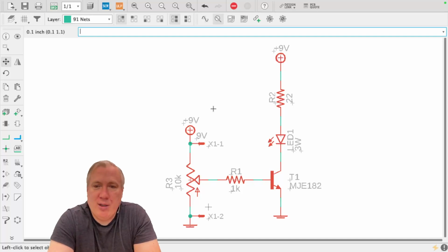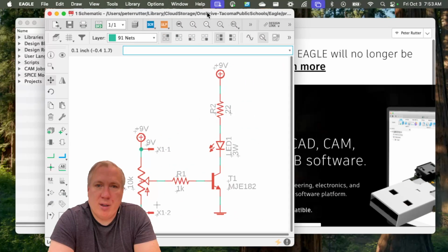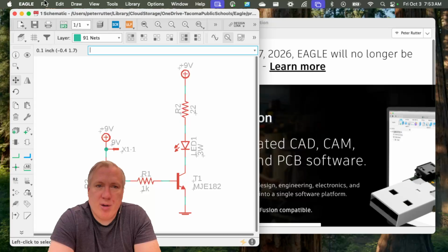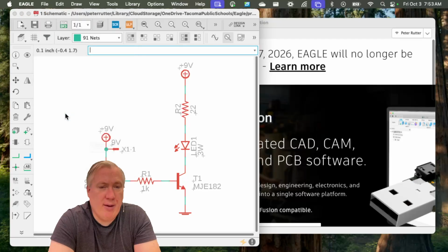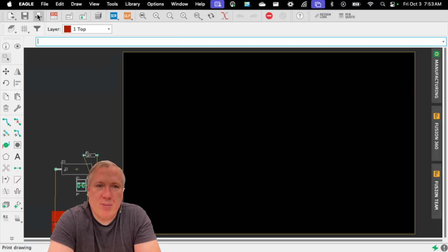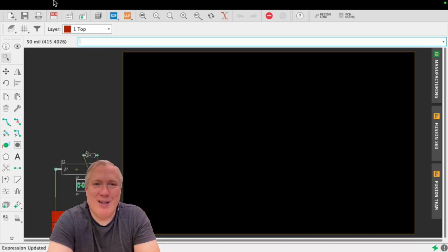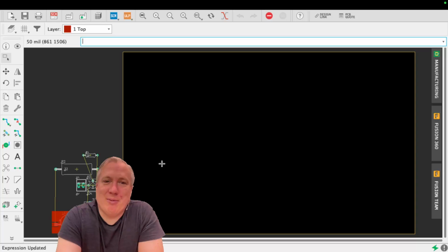The last thing we need to do to wrap up this video, to wrap up this phase, is to get our board. So I'm going to get out of this full screen here. I'm going to go up to File and switch to Board. And when I do that, it's going to say, hey, you don't have a board. Do you want to make one? Yes. Okay. And oh boy, that just did something. Eagle has some glitches for this type of system sometimes. Anyway, I'm not too worried about it. But now I've got my board.